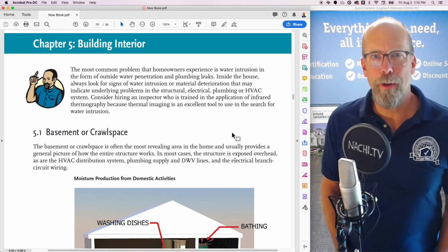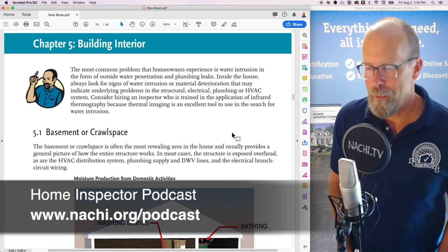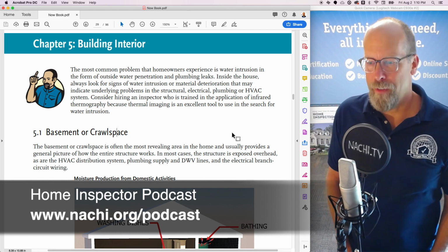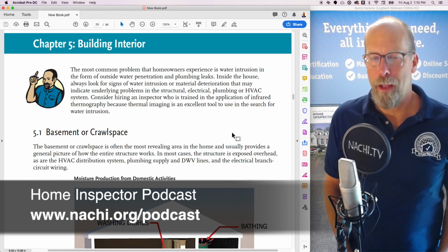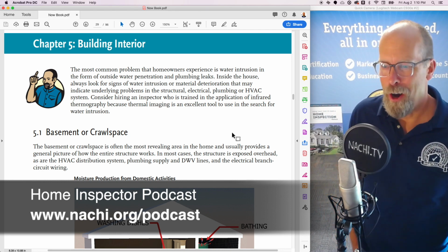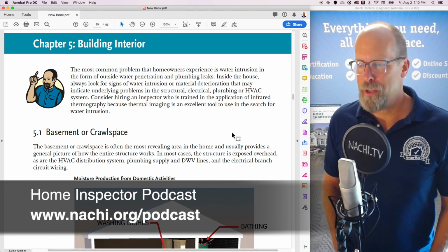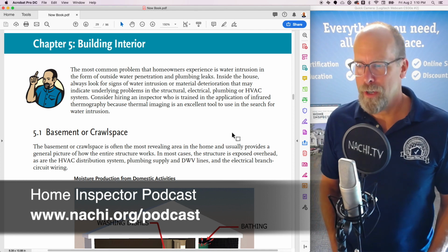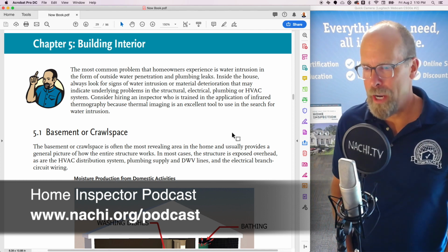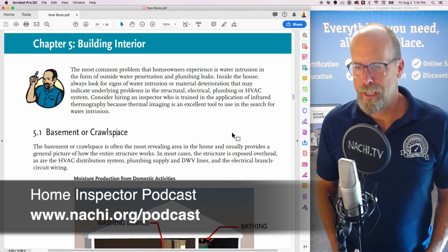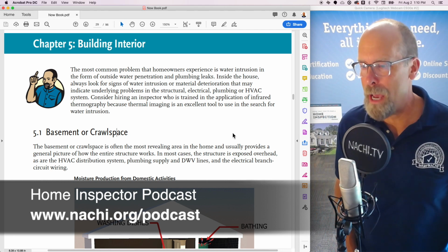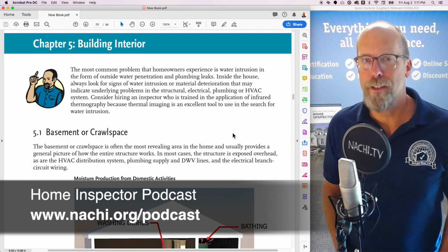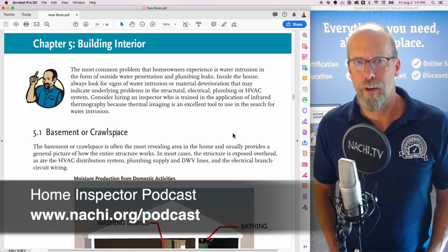Let's talk about the building interior. The most common problem that homeowners experience is water intrusion in the form of outside water penetration and plumbing leaks. Inside the house, always look for signs of water intrusion or material deterioration that may indicate underlying problems in the structural, electrical, plumbing, or HVAC systems. Consider hiring an inspector who is trained in the application of infrared thermography because thermal imaging is an excellent tool to use in the search of water intrusion.